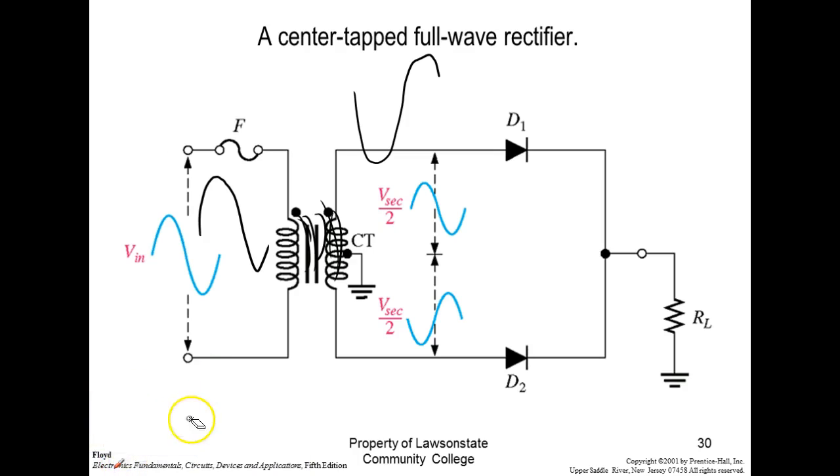And a lot of transformers are wound that way. It's just so convenient. They've got a couple of windings anyway, so they just wind them right on top of each other. And a lot of times you can see that. So the dot means we're going to use the same polarity on input and output.